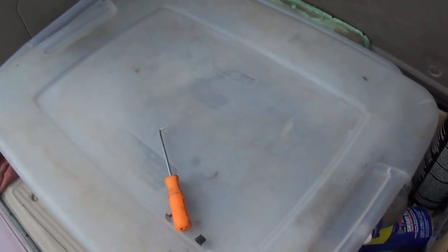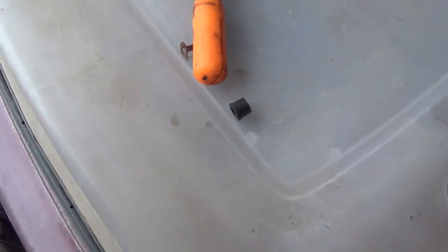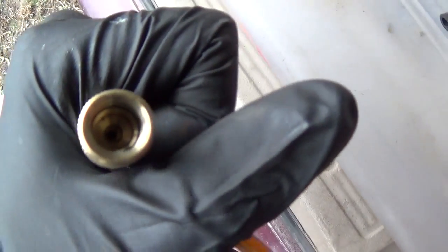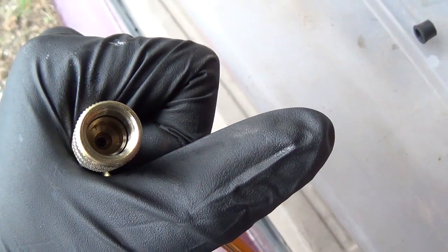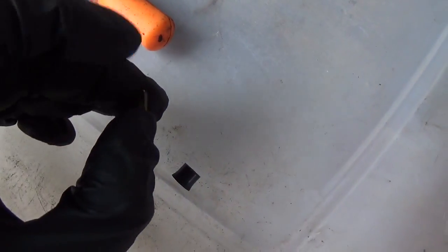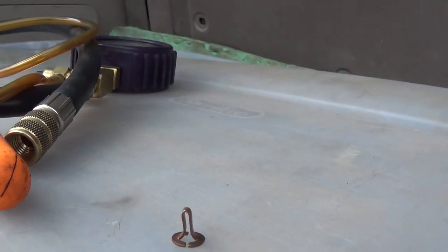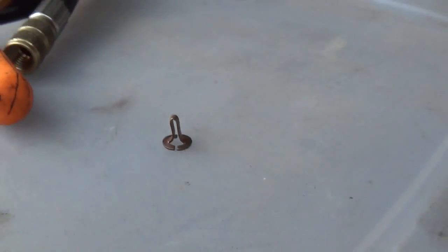So now I'm wondering, why is my fuel pressure gauge not displaying anything? And the little tip in here that's supposed to depress the Schrader valve kind of got bent out of shape a little bit. It's just this little metal piece. See how it's kind of crooked? It's supposed to sit straight. It's kind of leaning left, so I'm going to bend it back, reconnect it,